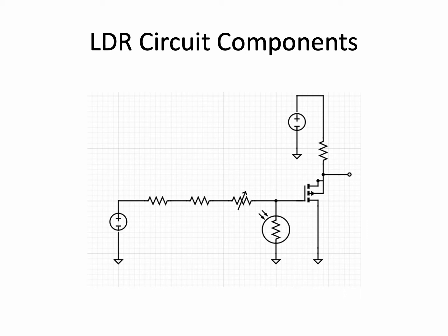As a result, the voltage on the drain will be approximately 3.3 volts as supplied by the Pi's 3.3 supply. This voltage, or any above 1.8 volts according to the Pi's specifications, is interpreted as a digital logic high. Conversely, when the light is not incident on the photoresistor, the voltage at the transistor's gate places it into saturation, causing the voltage at the drain to go to 0 and the Pi to read a logic low. This circuit can be tuned to the ambient light present in a room using the potentiometer, adding some robustness to the sensor's design.